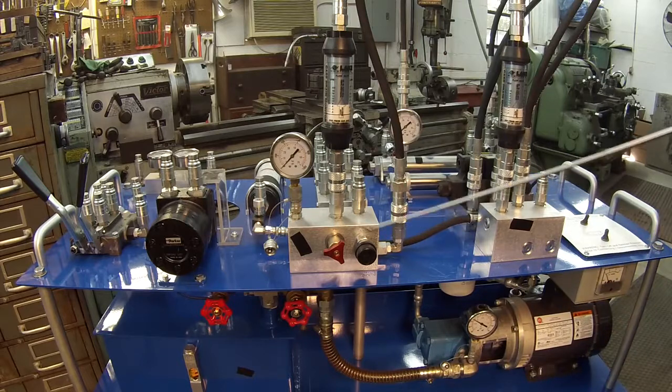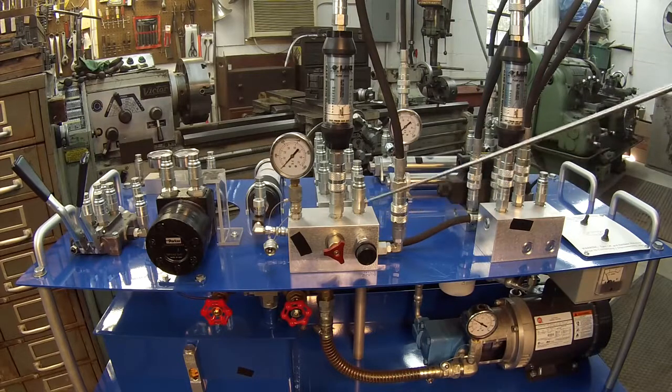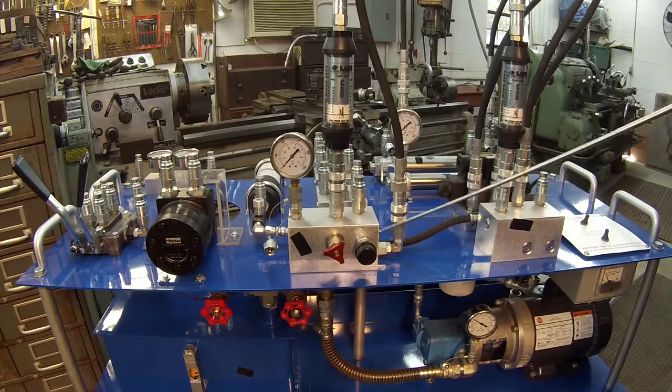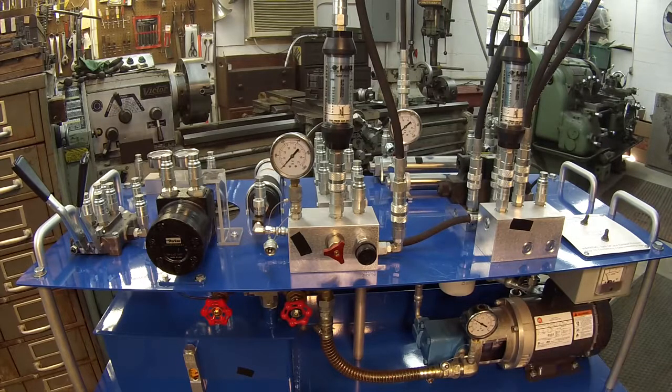The biggest failure that I have with these relief valves right here is the wrong pressure range. If I'm going to operate my hydraulic system at, say, 1500 psi, and I get a relief valve that goes from 0 to 800 psi, what's going to happen is every time you turn that system on, your fluid's going to dump over your relief valve, and nothing's ever going to happen out here. So it's very important to make sure your spring range is correct on your relief valve.